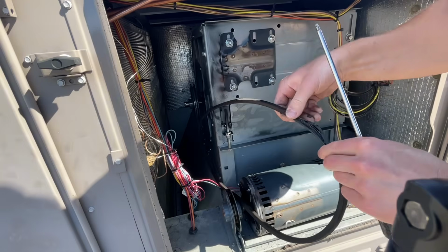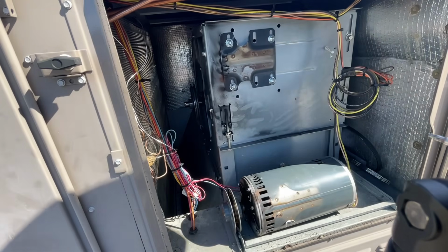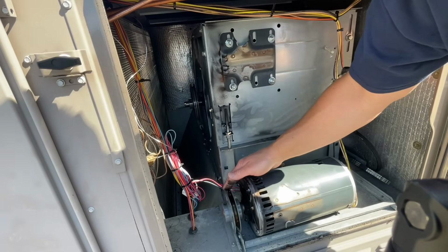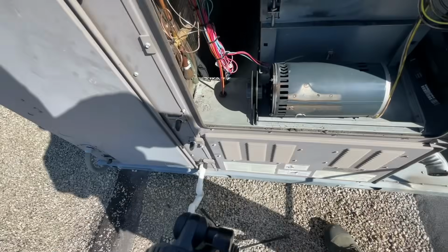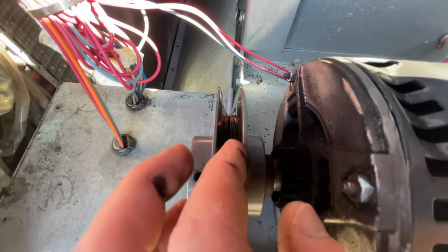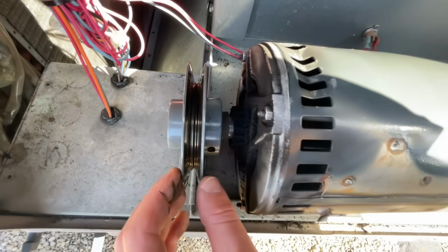Unbelievable. There's a little bit of damage. Oh, well, there's quite a bit of damage here, but see, I don't know if this is a pulley issue, but this pulley doesn't even look bad. Usually you can check these pulleys with their grooves. So you see how these grooves here still look fairly healthy on them, and it looks like this pulley is pretty new.